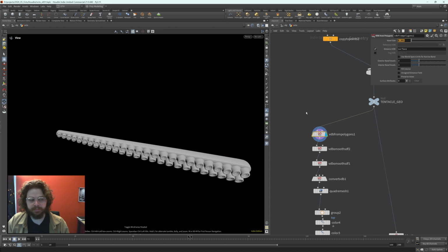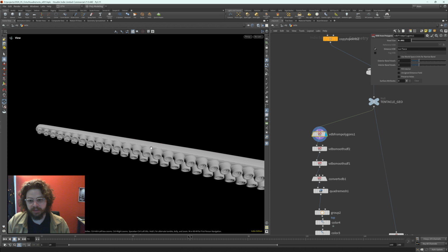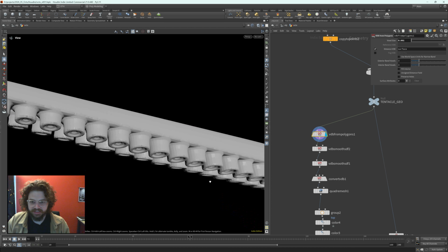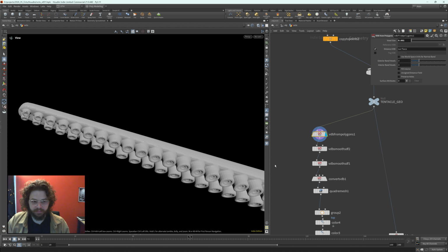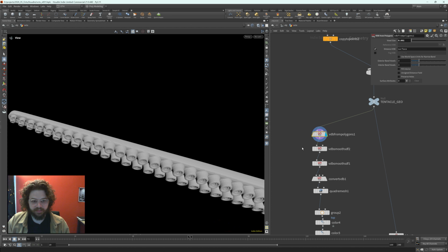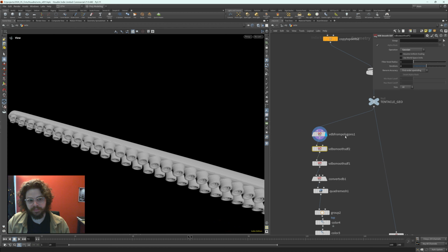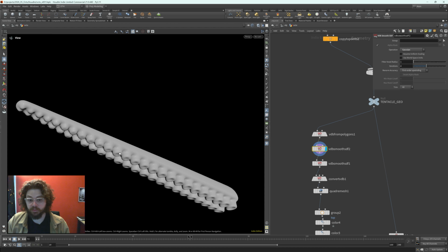You would have to adjust that based on the size of your mesh. And you can see that combines everything into this continuous VDB shape. And then I use some of these smoothing operations. So I use the Gaussian smooth SDF, which really sort of softens the whole mesh quite aggressively. And then I followed it up with a mean curvature flow smooth SDF.